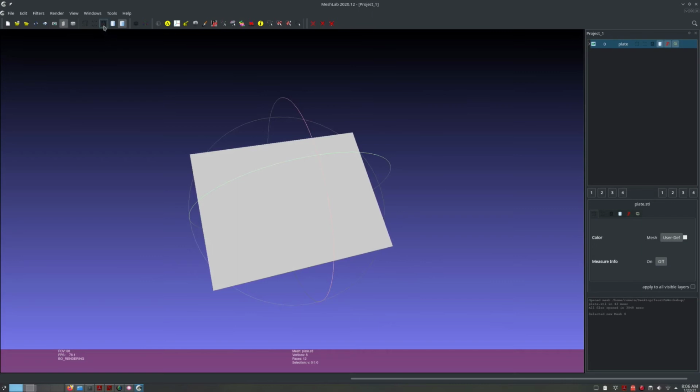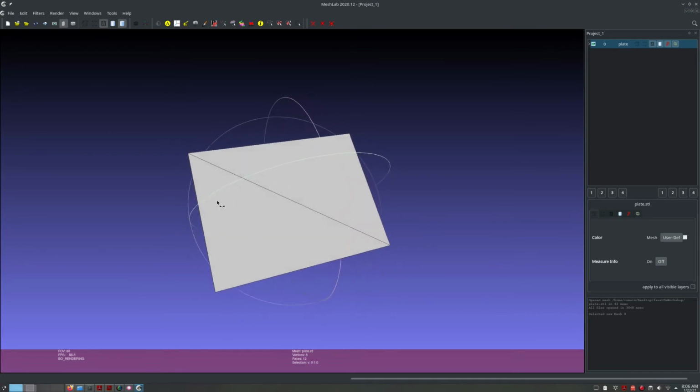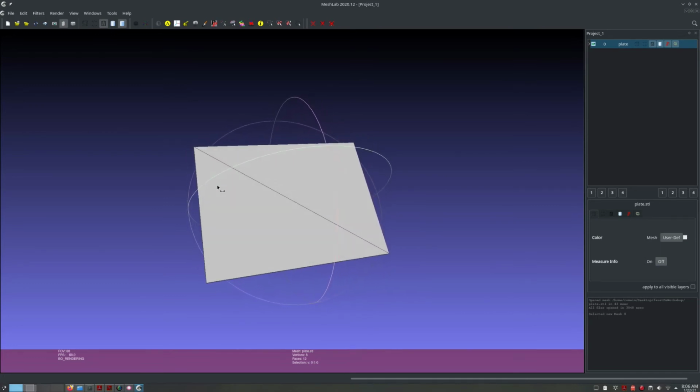And so in MeshLab, you can actually plot the triangles which constitute the mesh, and you see that for the top surface here, there are only two triangles, and that's what I meant by optimized mesh. Instead of having this, we want to have many small triangles that constitute the mesh, because we need to have a high density mesh, which is not what we currently have here.